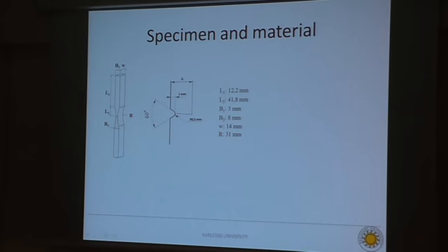The specimen that we are using is the fatigue crack growth specimen for ultrasonic testing. The rectangular cross-section gives us a plane surface to observe and measure the crack on. The sinusoidal part in the middle reduces the resonance length of the specimen, makes it shorter.